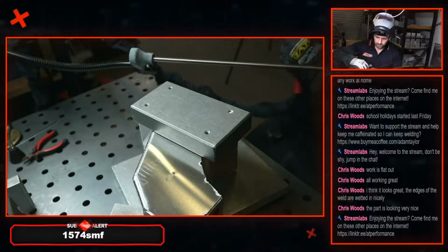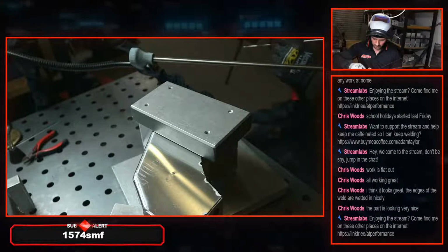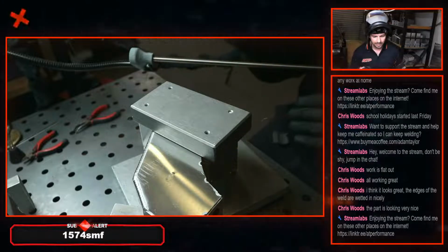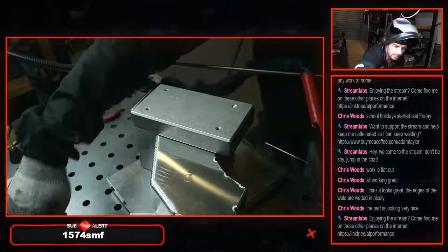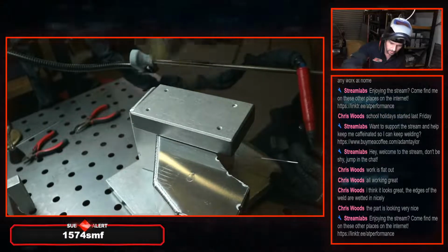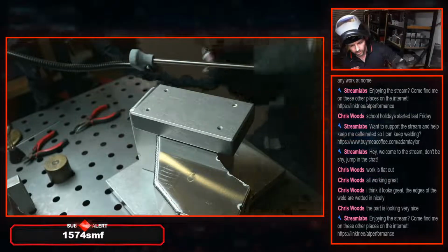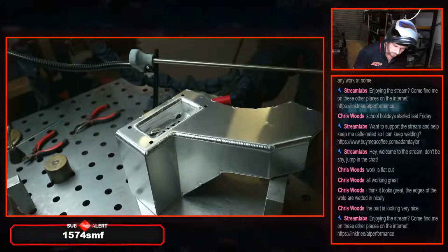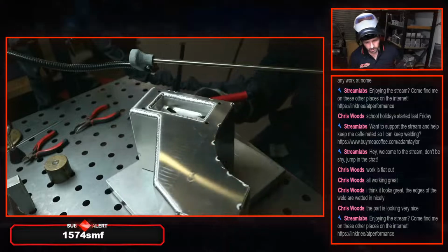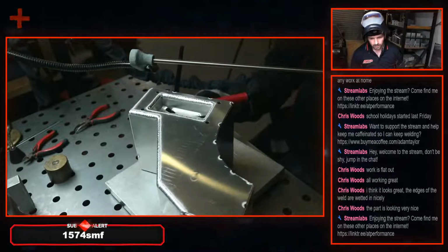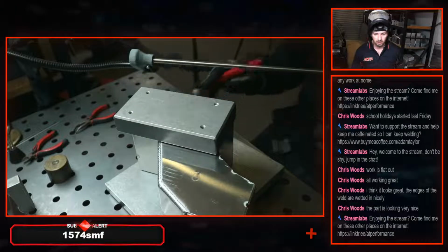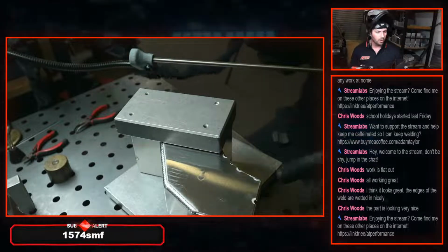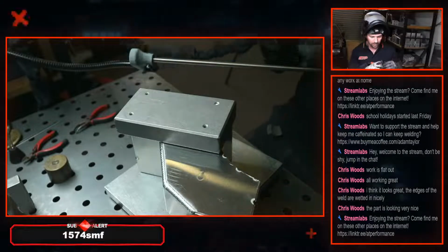So I might stick out a little bit too far, just dropping it back to about 3.5mm, 3mm, was about 4.5, just a little bit too far. I do notice a little bit of distortion in this top plate here as well. Tank number 1, so this is the one where we, whatever we did, I think we had 40% on time. Can't remember, I have to go back and watch the video, but we'll just keep going around the outside, just touch up these corners. I think I'll go all the way around this curve. We'll see how hot it gets at the end of this weld.